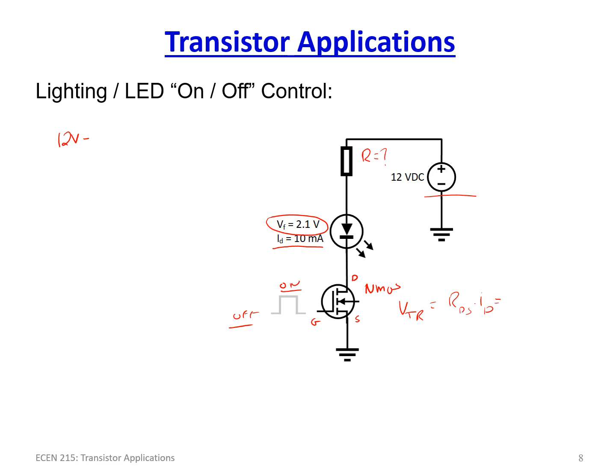So we're talking 0.1 amps times typically about an ohm, so about 0.01 volts. Not even really worth talking about. This is approximately equal to 0 volts. So the transistor is not anything of concern.